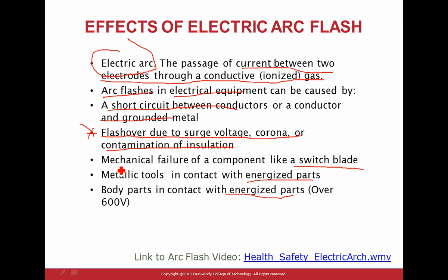Any comments, guys, about arc flash versus shock hazard? Arc and shock. I'm always scared if I open a panel. You go to 120 here, guys, I mean, arc flash, non-existent. But the minute that you open a panel, shock is still there. You could die. There are people who died from a 277 there.